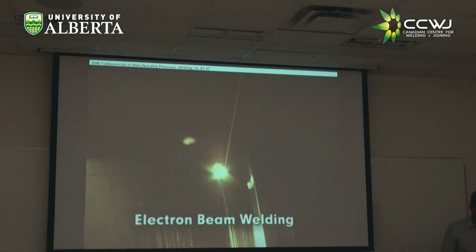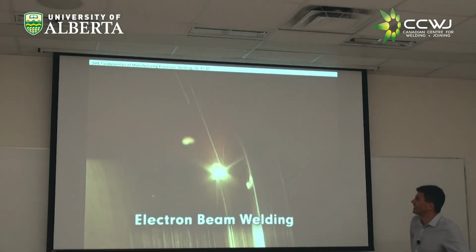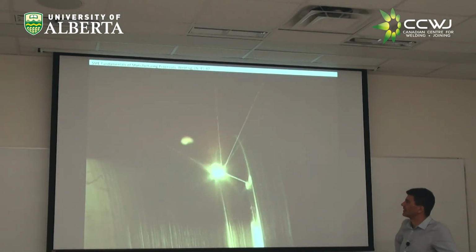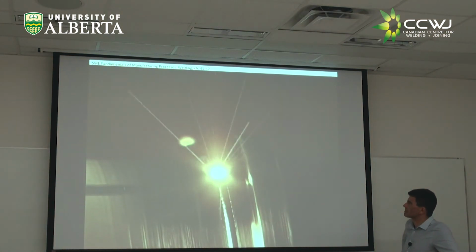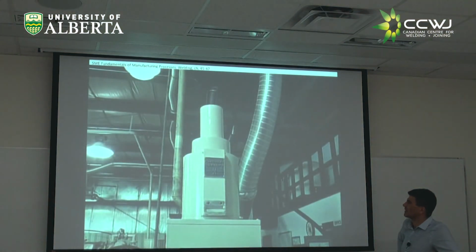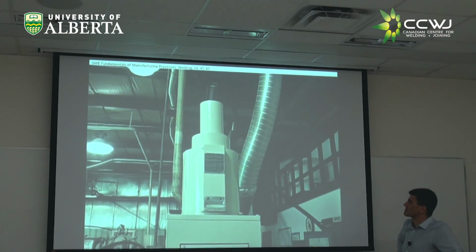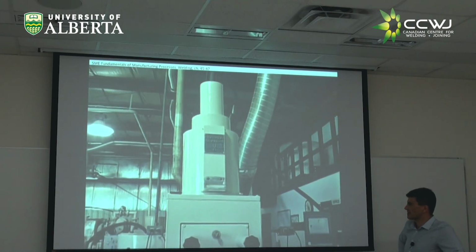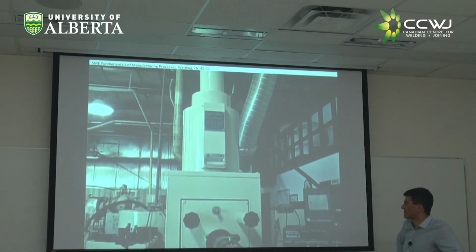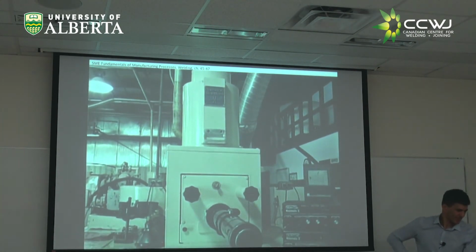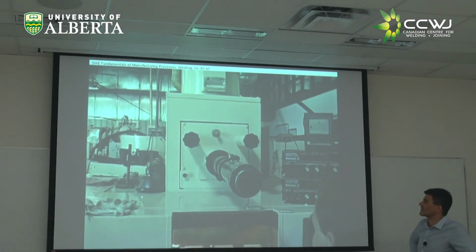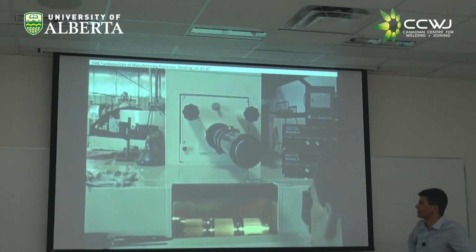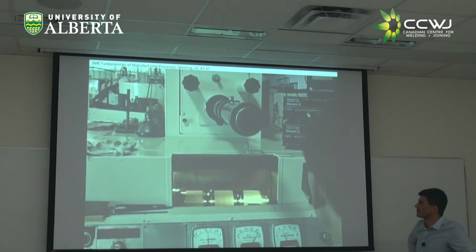Okay, here's something about electron beam welding. Coalescence heat is generated by the kinetic energy of a focused stream of electrons directed upon the joint. The electrons are produced by an electron gun, accelerated to high velocity, shaped into a beam by electrical fields, and then further collimated, or made parallel, and focused by an electromagnetic lens.